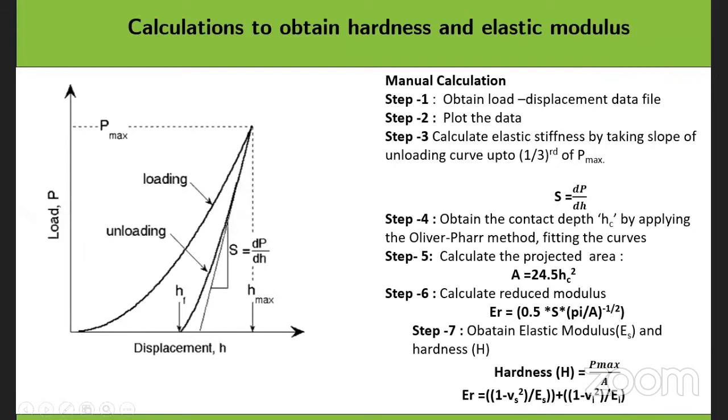You can go ahead. So another advantage of nano indentation, which I mentioned here, is that these days thin films are very popular, where the thickness of the film is on the order of microns, sometimes nanometers also, right? So when you're doing a normal indentation or high load indentation, you put the indenter into the material and it creates a strain field or stress field. The stress field will not only penetrate into the thin film, but also the substrate. So the final property you're measuring is basically a combination of both the film and the substrate.